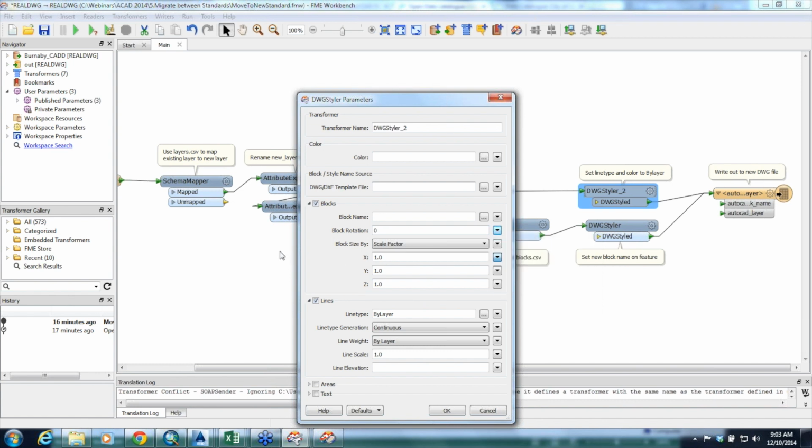Bill Kuchik has mentioned that if you are going just into Esri and you really want the annotation to look exactly right, there is a geoprocessing tool that you can use to skim the annotation and mirror it exactly. Actually, this is a weird thing with ArcMap. If I read the data initially into ArcMap, the annotation looks a little screwy, but if I save it as an MXD and then reopen that MXD, the annotation just looks peachy. I don't understand why, and I'm running an older version of ArcMap, so it may be that.